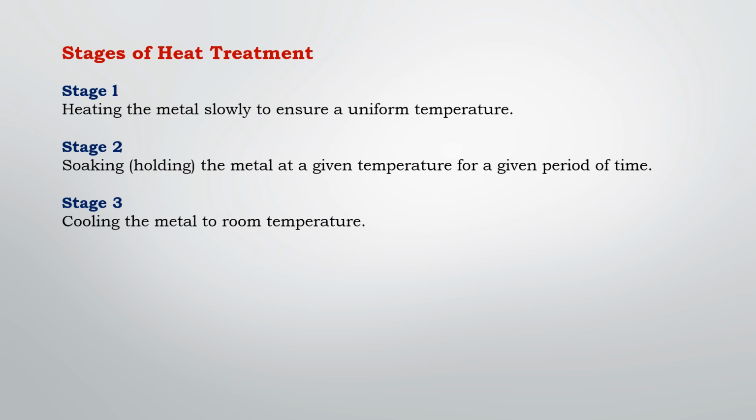Soaking is the stage at which the complete part of the heated metal completely changes in its structure. The mass of the metal will determine the time it will be soaked. In other words, soaking is when a part of a metal evenly becomes red due to it being subjected to heat for some time. The third stage of the heat treating process is cooling.